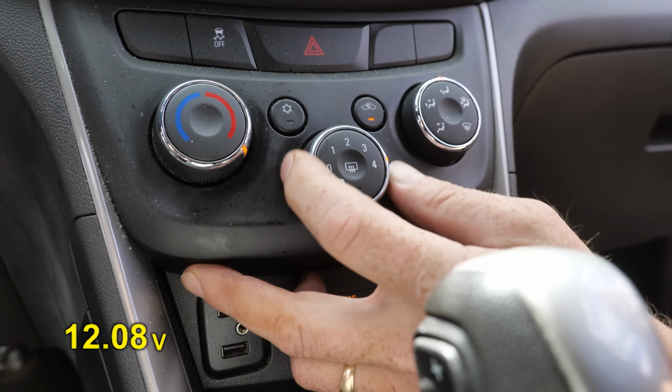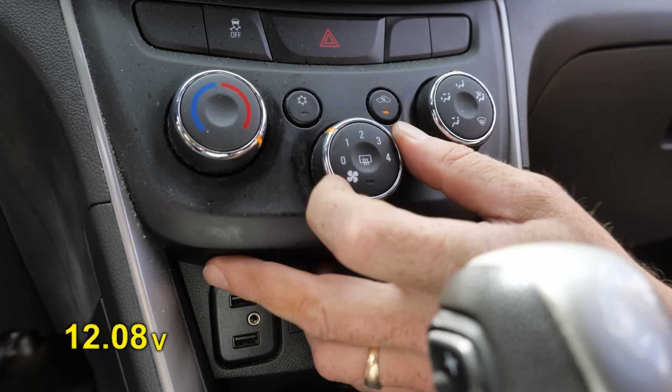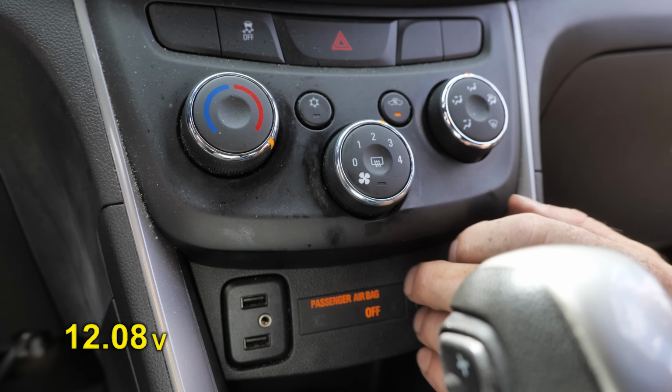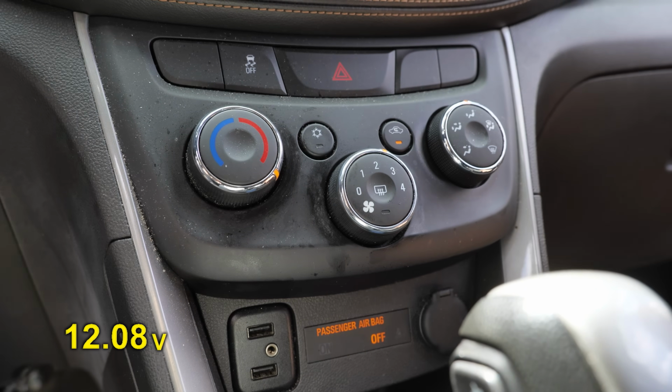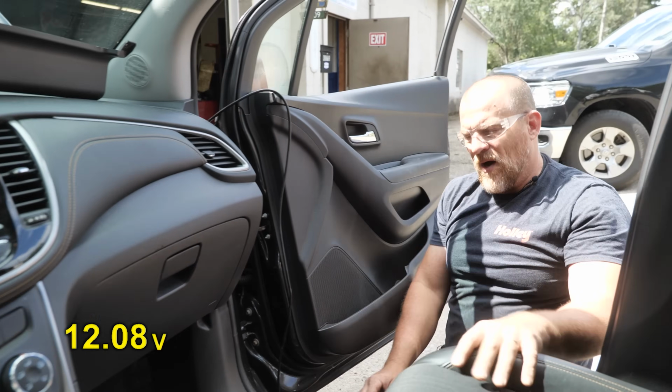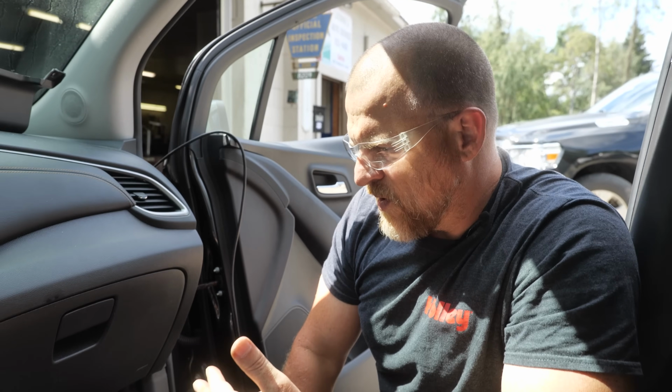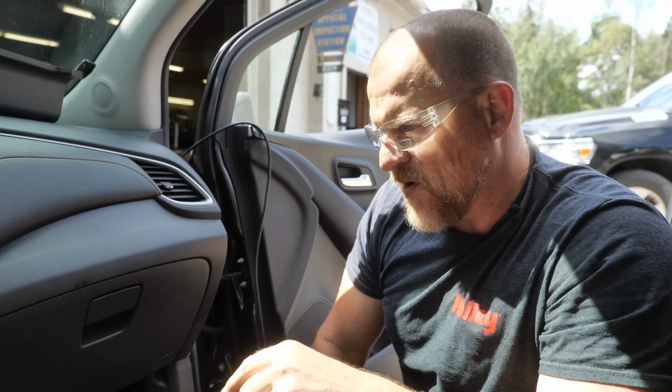So what that's telling me, again, is that we have a ground, our switch is working fine. We have a ground on the resistor bank through the blower switch, and our problem is internal, again, between the 2 white black wires. So now I'm gonna pull this out. And then we have to address airflow. If this is burnt, we have to address airflow, and we have to address blower current.